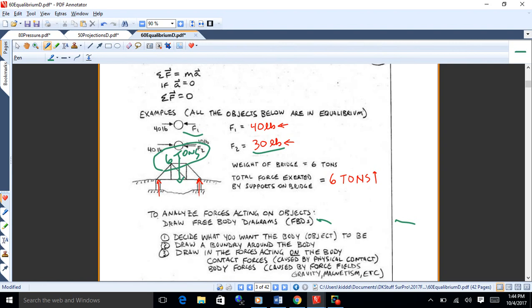For this building, the loads were the weight of the structure. That's called the dead load. The weight of the furniture and the people and the vending machines and the equipment and all that, that's called live load because it can move around. And then there's a snow load on the roof, and there's a wind load on the side of the structure. And we hope it doesn't happen anytime soon, but there might be an earthquake load on this building at some point, et cetera, okay?